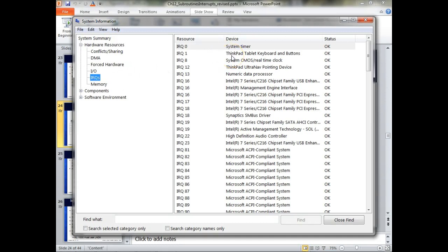Now this guy here never runs the keyboard subroutine until I do what? Until I hit a key. As soon as I hit a key, the keyboard controller generates an interrupt. And then the processor says, well, who did that? Inside the chipset, we have something called an interrupt controller that says it was interrupt number 1. You understand? That would cause the routine to run that just does what? Scans my keyboard, brings in the keystroke, then it turns it loose, right?